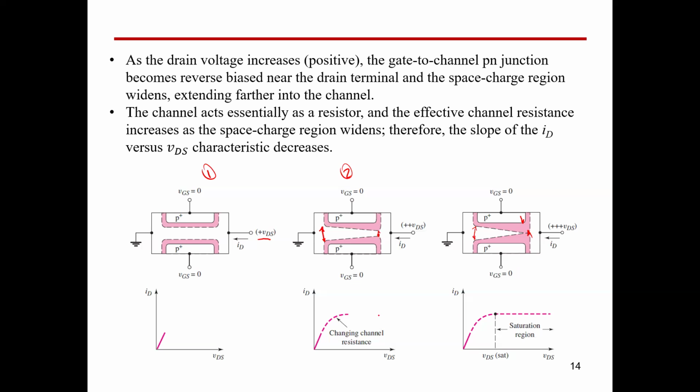So this is a complete trip of the JFET from VDS equal to a small value until very high values. Starting firstly with a small value of drain to source voltage, we are working in the linear region. Increase the drain to source voltage, and the channel here will decrease because the depletion regions will be wider compared to the previous case, because it's more reverse biased here.